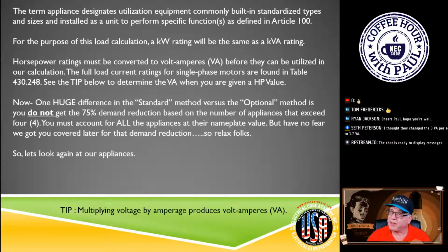So you're going to take the nameplate rating of all of your appliances. We'll look at the code in a second, but you're going to add all these appliances. Ultimately, you're going to take the nameplate ratings also of the cooking equipment, all of that. You just take it all. You'll see. Simple. This one's easy, right?